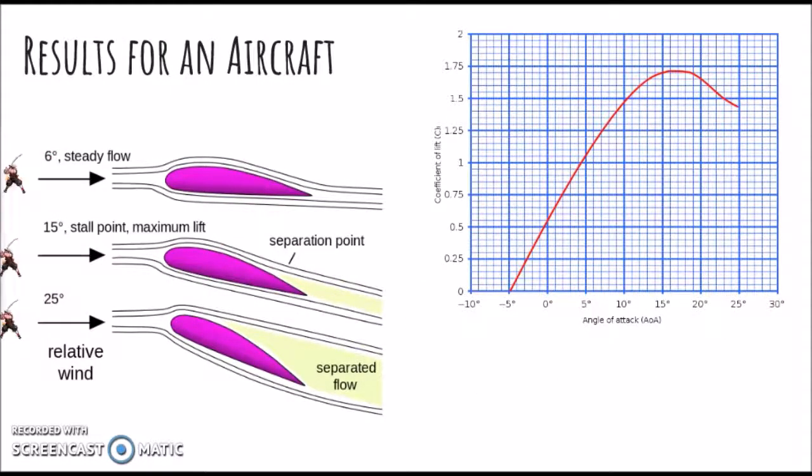The amount of lift the airfoil creates increases as the angle of attack increases until a certain point where the flow behind the airfoil begins to separate and the lift decreases. This point is called the critical angle of attack. Once the flow behind the airfoil separates, the separated flow dominates the characteristics of the flow, such that increasing the angle of attack more actually produces more drag and less lift.